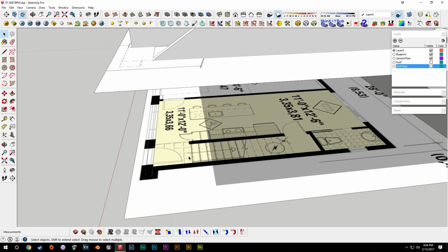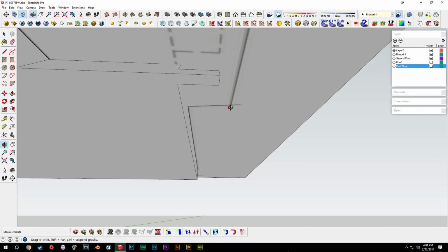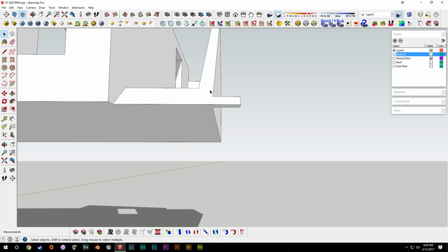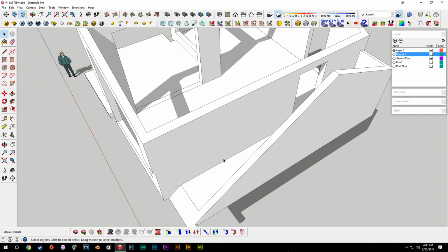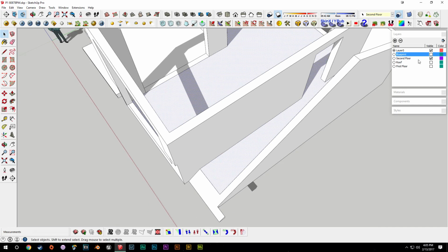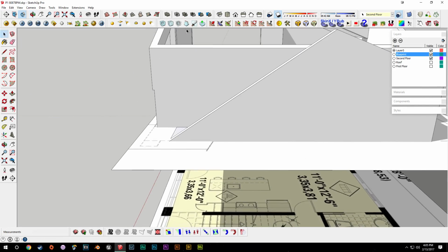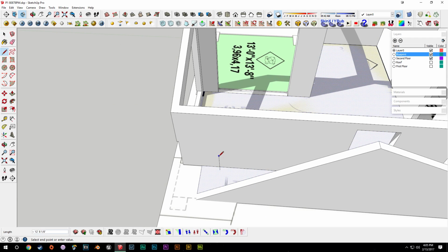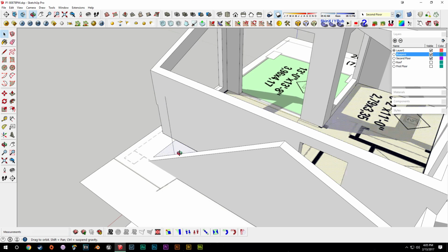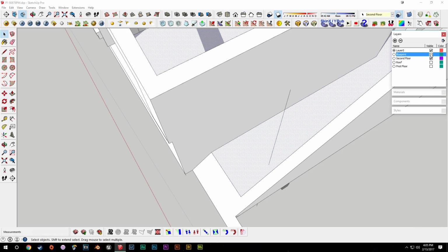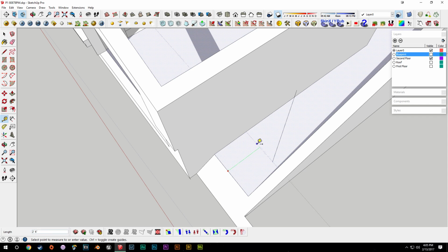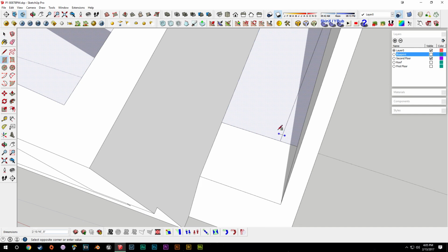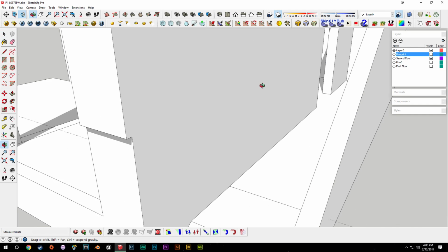And there are 13 steps, so what we'll do is go into the second floor, turn the blueprints off, and figure out where the stairs begin. Let's do a really rough line up, make sure it's on the blue axis right there. We can turn the blueprints off again, and drag a guide in from here, so it's roughly there. That's fine. Draw a line across.